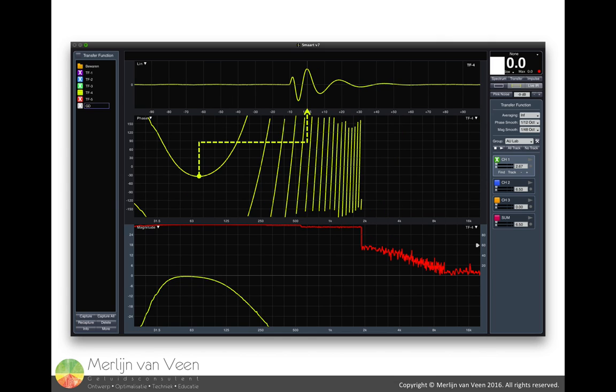If we move even further, we end up in the center of the passband, and now the phase response at 63 Hz shows a flat response, no elevation, no inclination, and all the frequencies to the right of 63 Hz are leading, and all the frequencies to the left of 63 Hz are lagging.